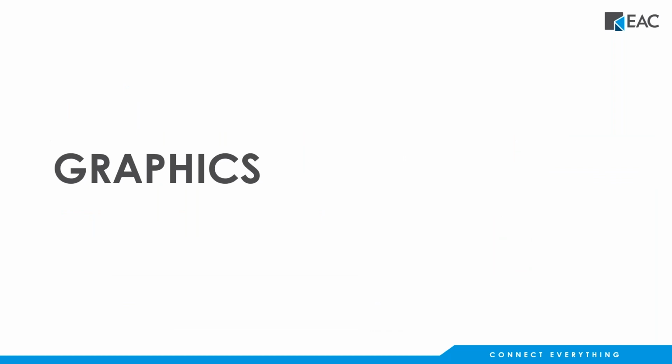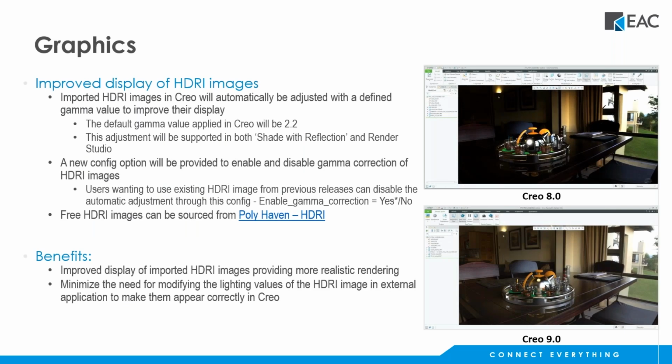All right, moving on to graphics. Creo 9 has some enhancements around the graphics. So we have an improved display of HDRI images. So now when we import HDRI images into Creo, they will automatically be adjusted with a gamma value to improve their display. The default gamma value is 2.2, but that can be adjusted through the shade and reflection options in Render Studio.